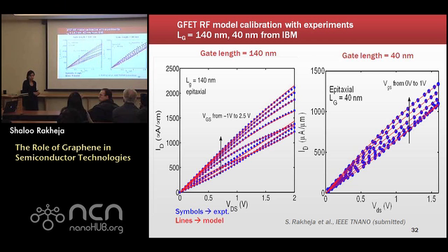For this shorter channel one, the 40 nanometer one, the on-off ratio becomes so small. It's because of the large contact resistances. Yes, these are very contact limited devices. For shorter channel lengths, we have not been able to successfully see any saturation effects. So another question that comes from this is, how do you know what your injection velocity is for these devices? Those are some very physical, fundamental questions that we need to ask ourselves. So we don't see any saturation, that's true.